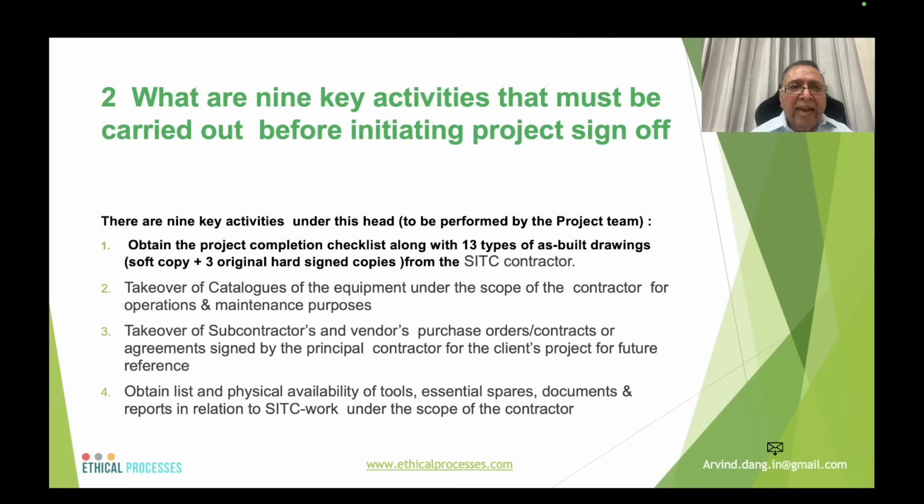What are the 9 key activities that must be carried out before initiating project sign off? Of course, this is to be done by the project team. Now, one, obtain the project completion checklist along with 13 types of as-built drawings, which include soft copy plus 3 original hard signed copies from the SITC contractors in the context of India.